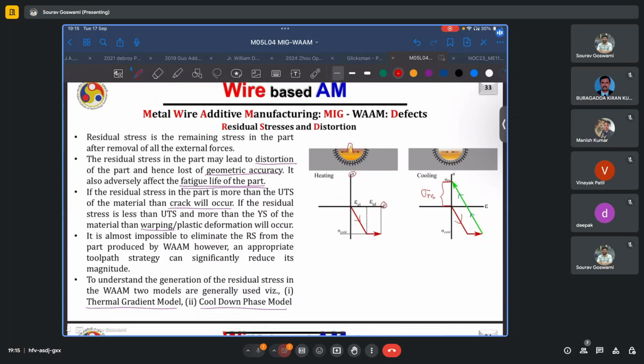Now, if the residual stress is tensile, as shown here, this is a problem because, as we know, no microstructure is perfect. Your build part will often have some small pores or some build cracks. And in the presence of tensile residual stresses, these cracks will continue to grow.